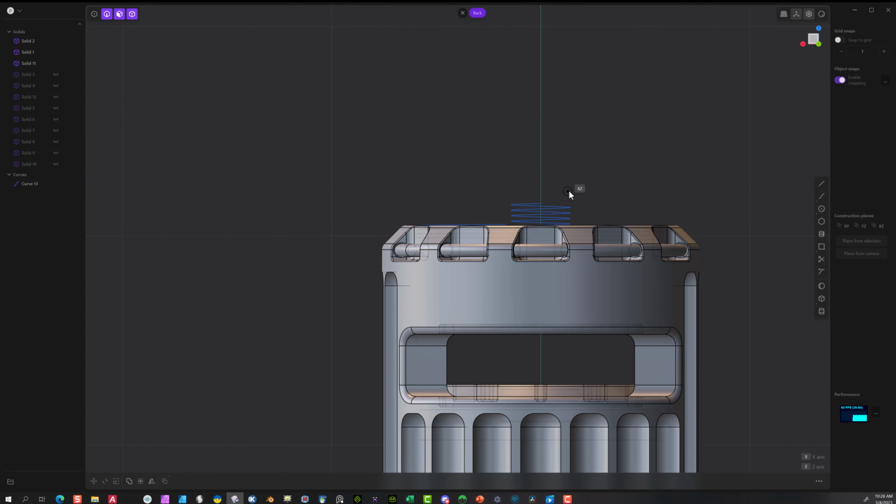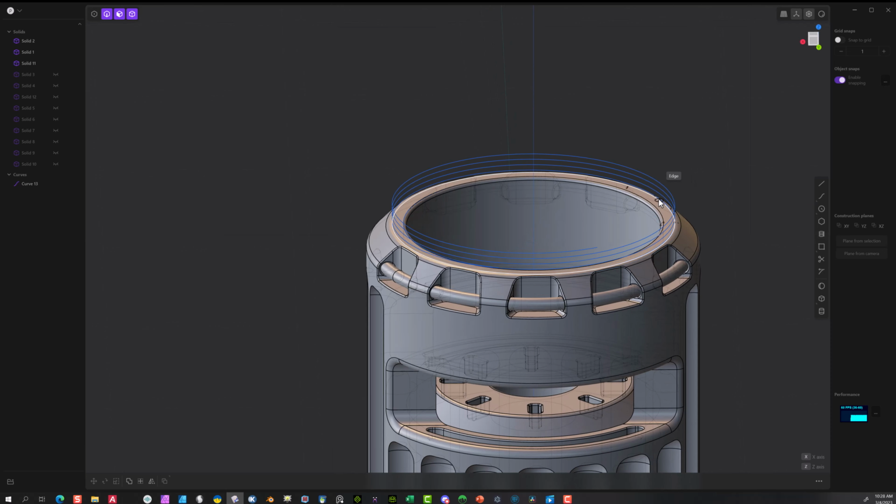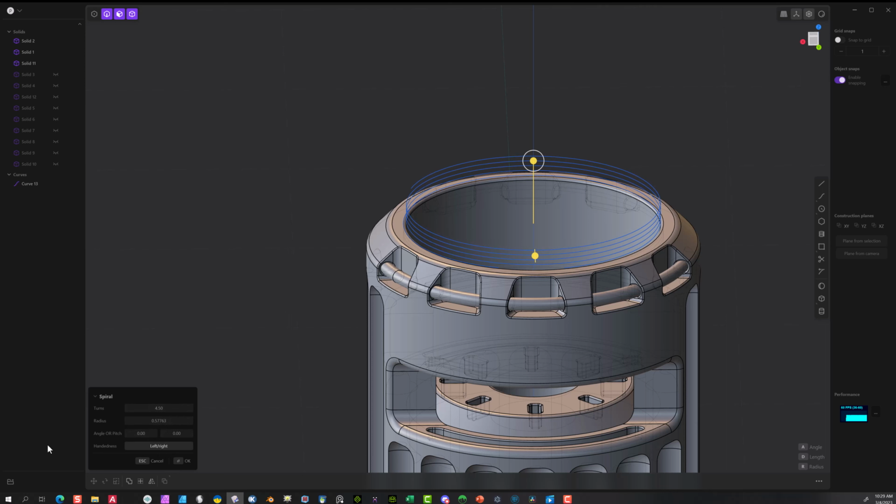and we're going to click in the top there in the center, and we're going to bring this out. One thing we want to make sure we do is get close to the inner, like that. So one thing I'm going to do is add more iterations on this. I think we're going to do double. We'll go with 8.